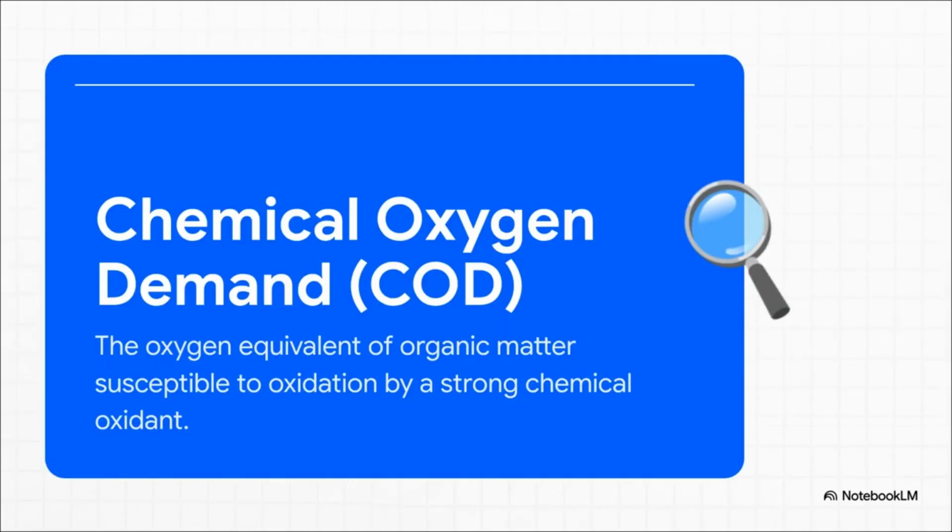Now let's talk about COD, the impatient cousin of BOD. Who has 5 days to wait for an answer, right? With COD, we use a really strong chemical, potassium dichromate, to just blast apart and oxidize all the organic matter. The big advantages here are speed, you get your results in just a couple of hours, and the fact that it measures non-biodegradable organics that the BOD test would miss.